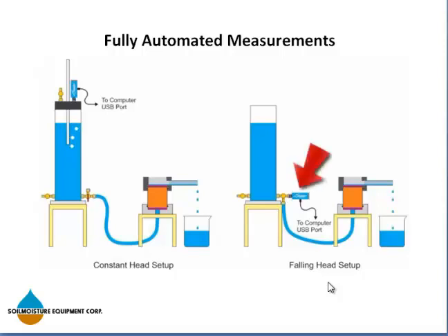The monitor transducer is connected to the base of the reservoir and it measures pressure. Mobility of the monitor transducer is one of the unique features of the Chameleon. This is the reason for the Chameleon being able to perform both the falling head and the constant head methods completely automatically. As a matter of fact, the monitor transducer can be connected to a third-party reservoir and the system still works.